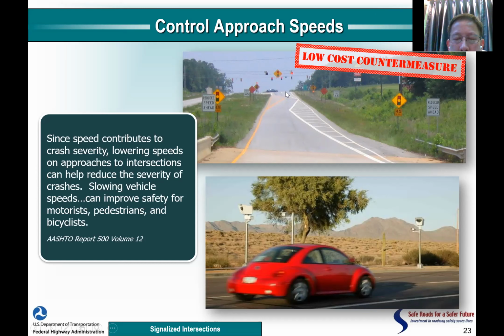So to avoid any unawareness of the through traffic. Sometimes when you drive for a long time without stopping at all, you find that in front of you there's an intersection. Engineers may put signals, but they have to have a good warning that there's a signal in front of you. So when you put a sign like this and the zigzag marking like this, okay.